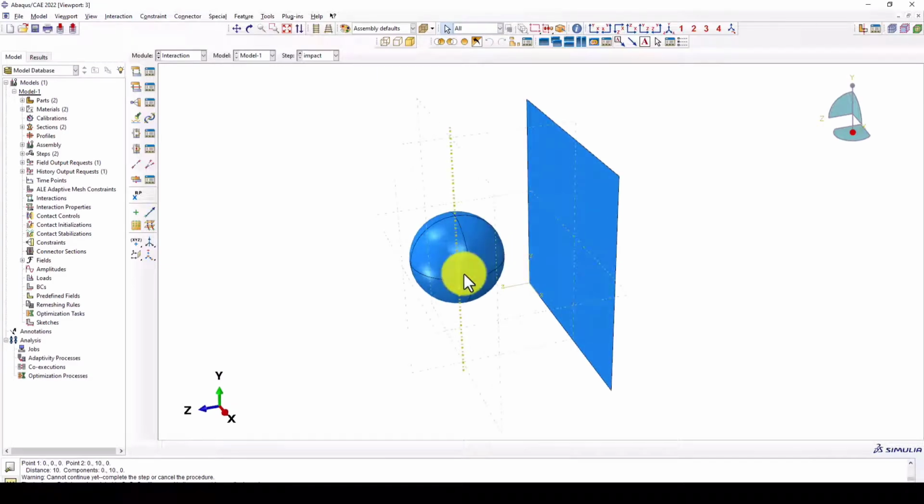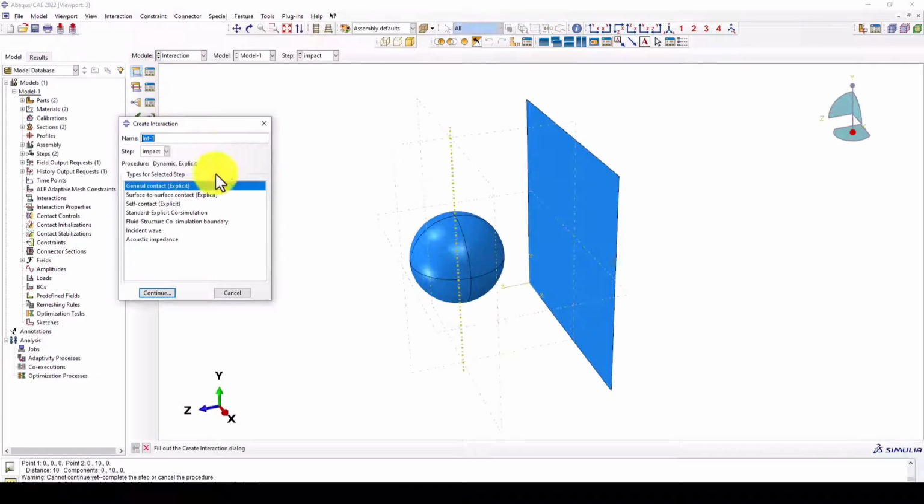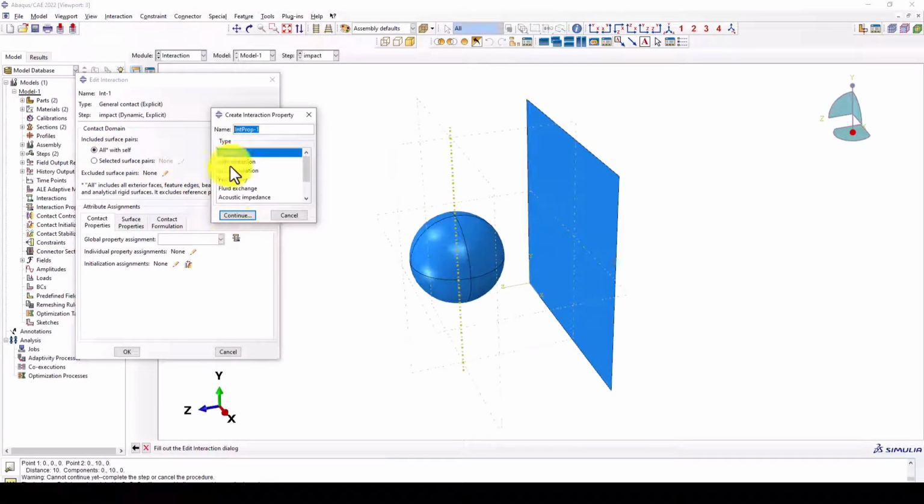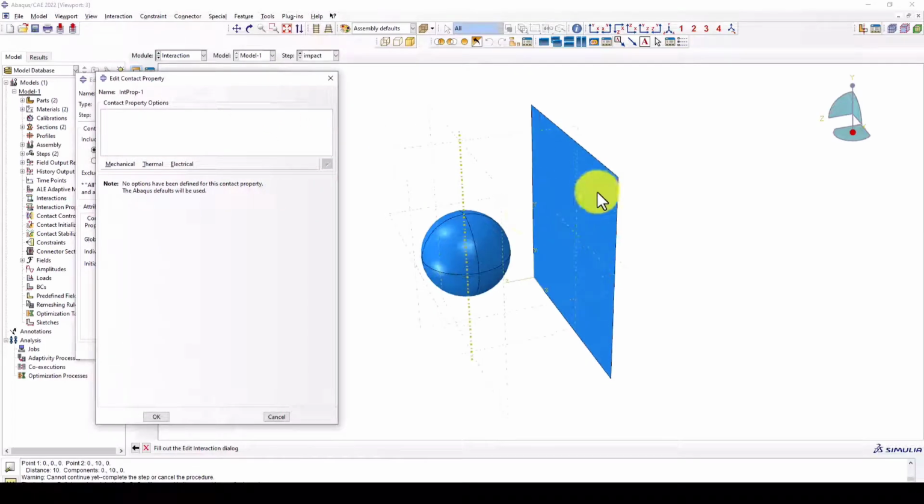A rigid body does not require a conventional deformable body mesh for its structural deformation. Instead, its motion can be controlled through a reference point, or RP. The rigid body can translate and rotate about its reference point. This is where RBD concepts become very useful.